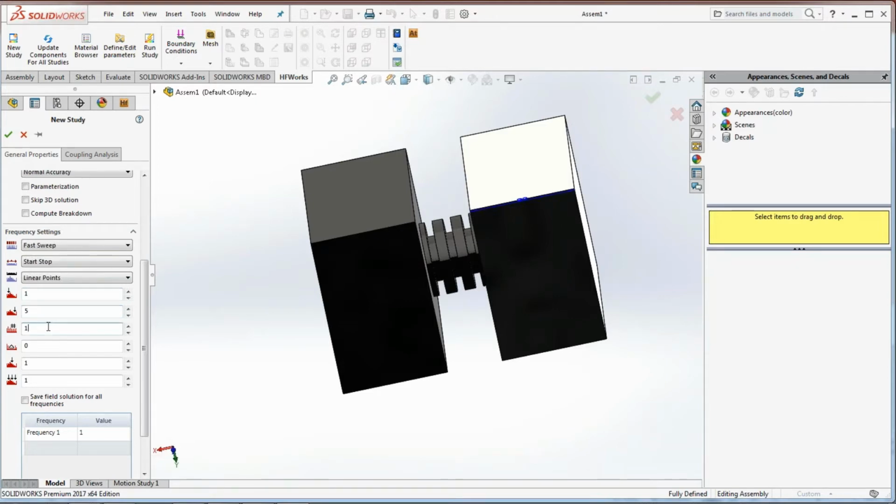And I want to see, like, let's say 100 frequency points in between. So it automatically decided that it's going to use 3 as the expansion point. And actually, I can increase the number of expansion points to increase the accuracy of my fast sweep.